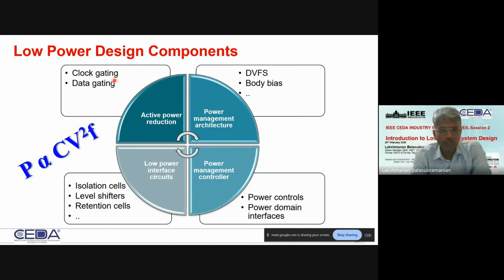And in combination, now you have the power supply level control and the activity control, which is frequency control and voltage control, right? That now can be done in a very fine-tuned way. That's called dynamic voltage and frequency scaling. There is also another fact that when you reduce the voltage of operation, the leakage comes down. I mean, that's known from the equation.